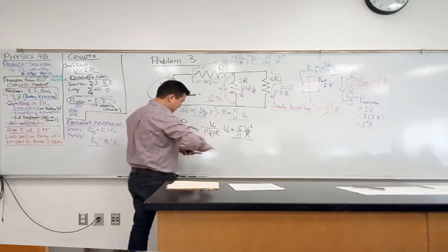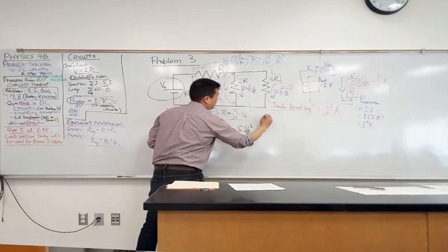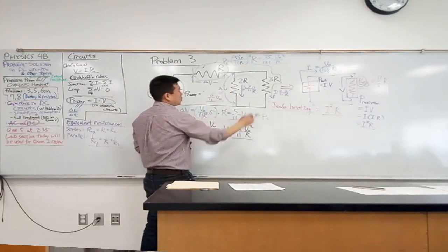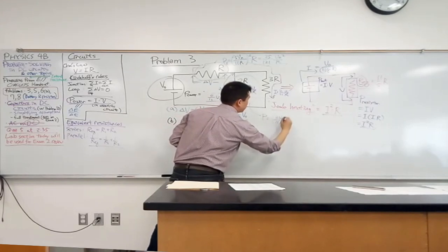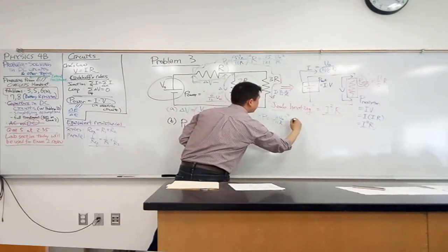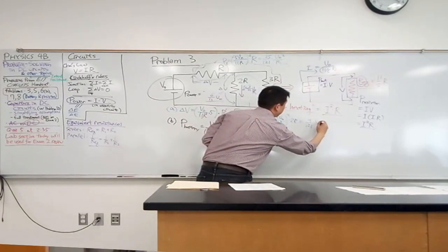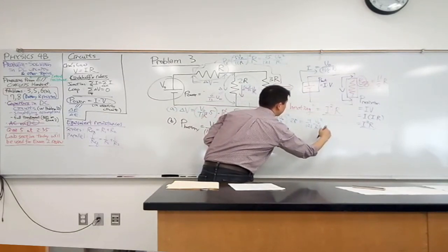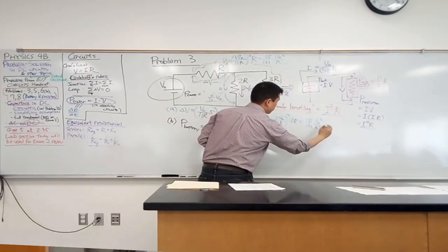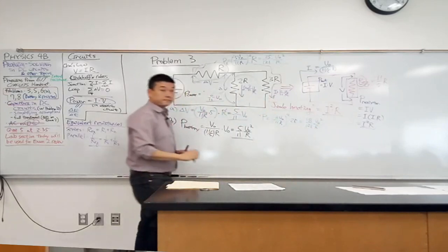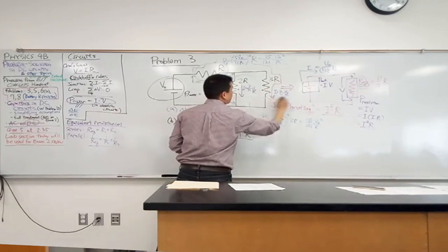Then the power that's dissipated through the resistor 2R should be once again the current squared times the resistance. So 3 V naught over 11R, squared, times 2R. That would be 9 over 121 V naught squared over R squared times 2R. So it'll be 18 over all of this, and R cancels one of these. Okay. Let me do it for the third one, and we'll add it up and see that they agree with each other.